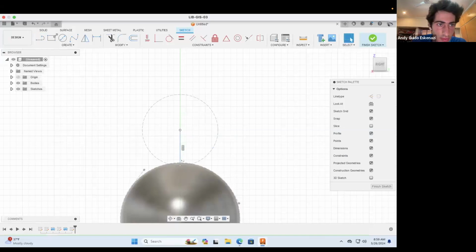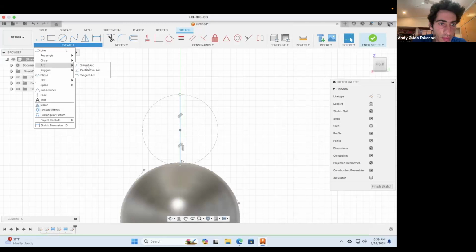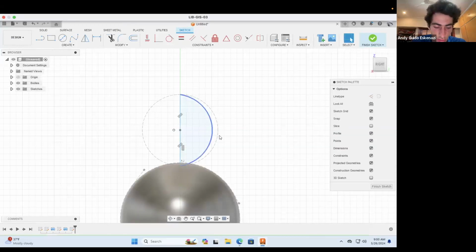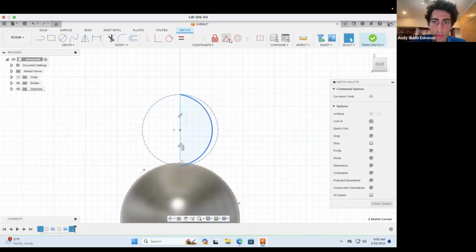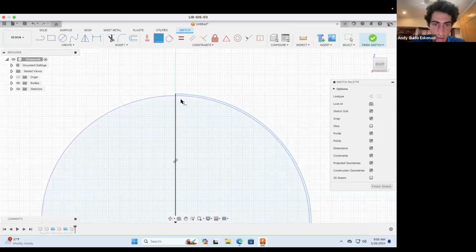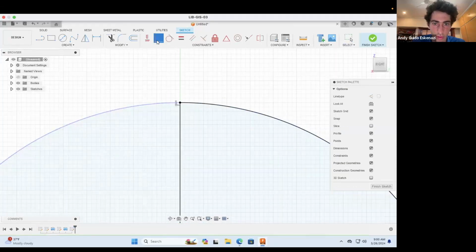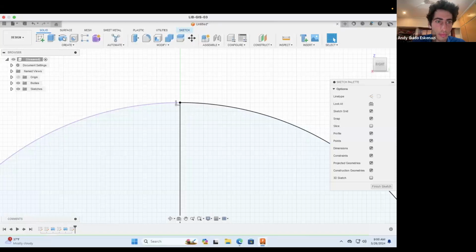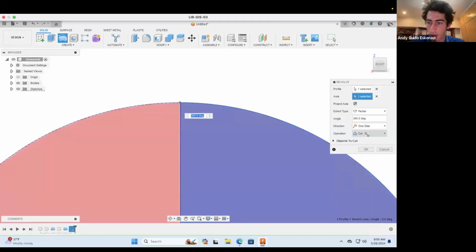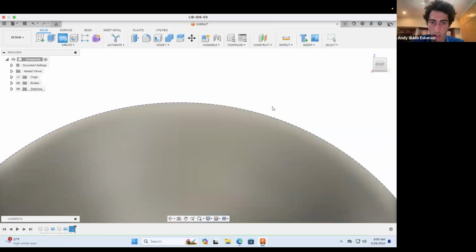Make that go there. And then I'm gonna add another point that goes all the way like that. Boom. And our 3-point arch. It goes all the way from here to here. Right, so let's click on these two, make it concentric. Then this point and this point, we do coincident, and the same thing in here. Coincident, excellent. Right, solid, revolve, axis, this one, and I'm gonna make a join. Okay.